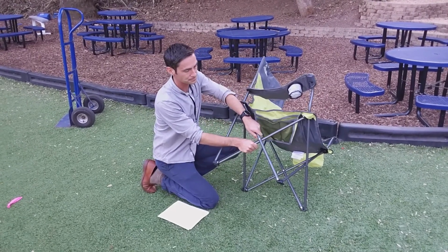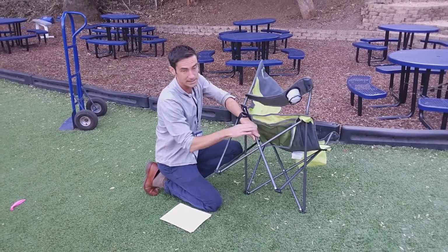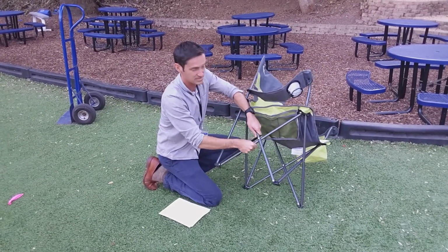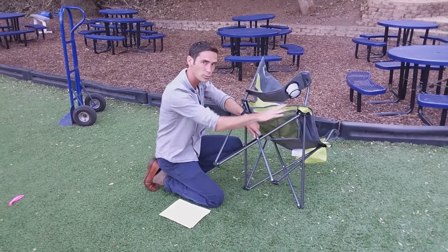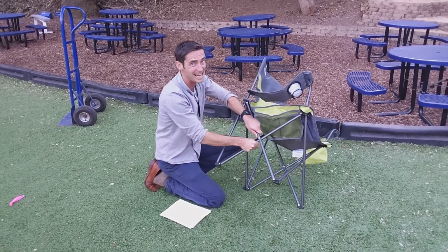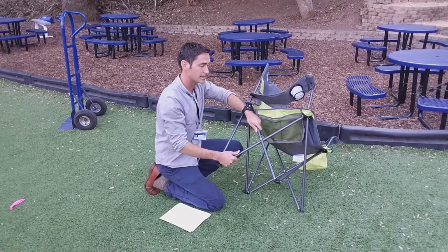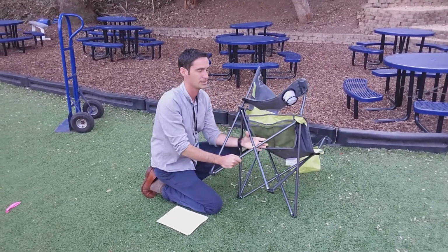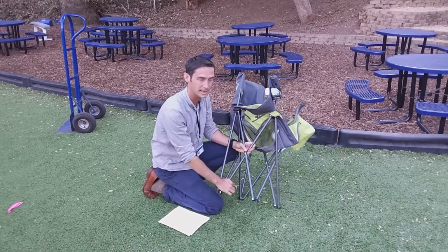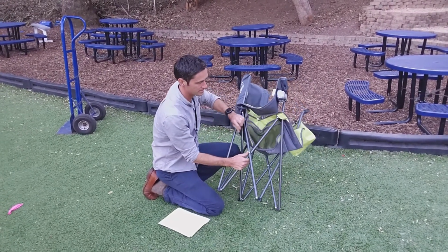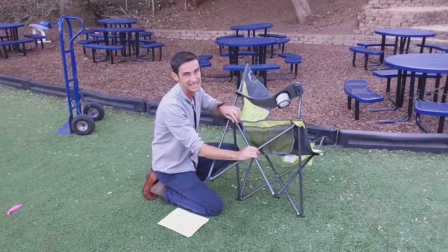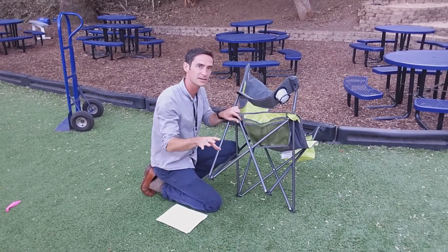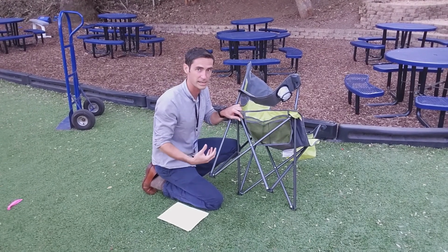You cannot translate, like slide these things apart. Up, down, left, right, this way. Okay, picture the X, Y, Z. This cannot slide in any direction. It also cannot rotate in most directions except this. Okay? It can rotate that way, and that's it. One rotational degree of freedom, and then all the other 5 are constrained.